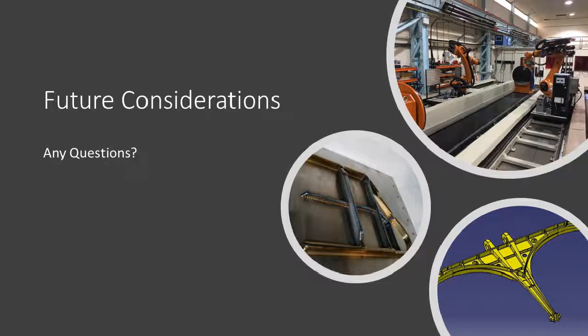So probably the closest we can come to anything with structural integrity would be the running guards for the shafts. So the cross-drive shafts that take power from the gearbox to the APU and across to the other gearbox. We use those as debris guards. So we've gone for toughness as the material properties over any load-bearing capability.